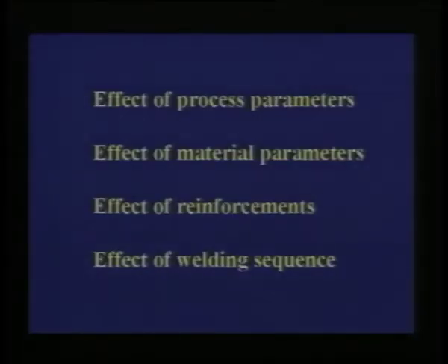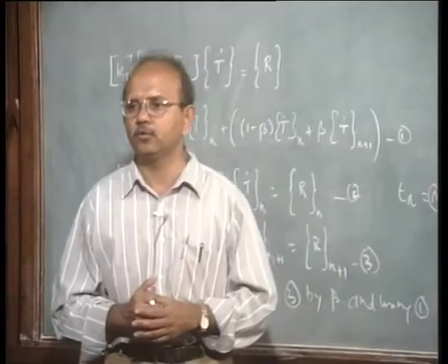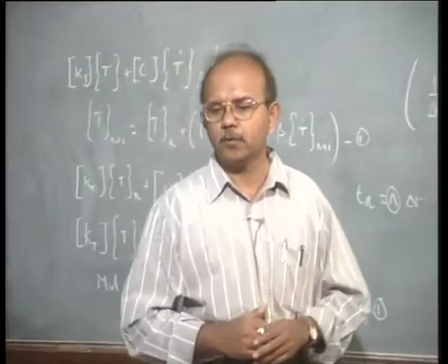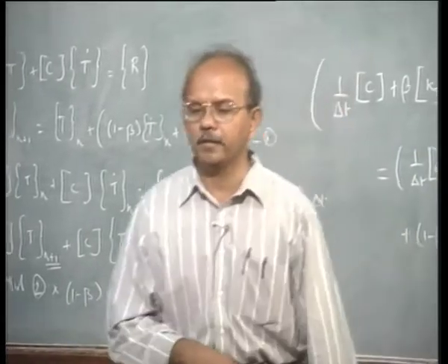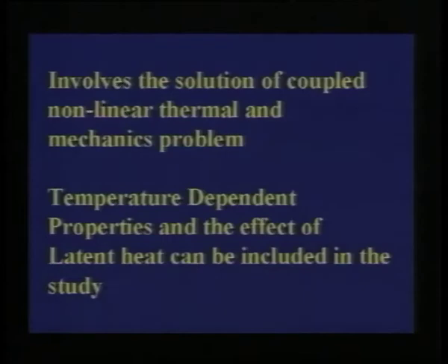And you can also study the welding sequence. How do you sequence this welding? There are different ways in which people do this welding, and that also it is possible to study. Let us look at the next slide and see what is further involved in welding simulation. Basically, I have been telling that this welding simulation is a coupled problem. We have to solve both the thermal problem as well as the mechanics problem.